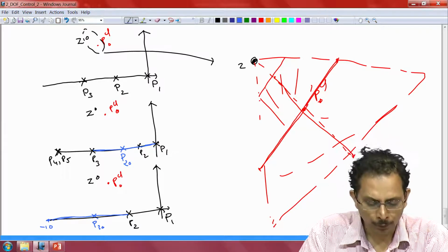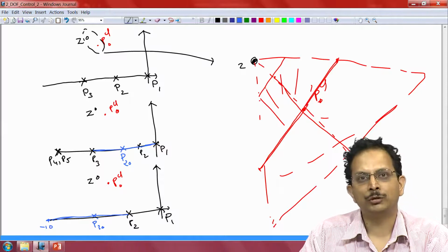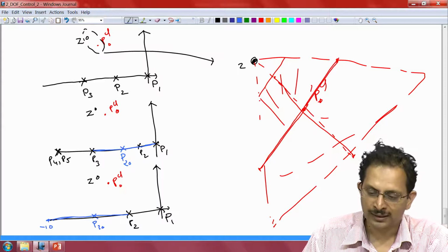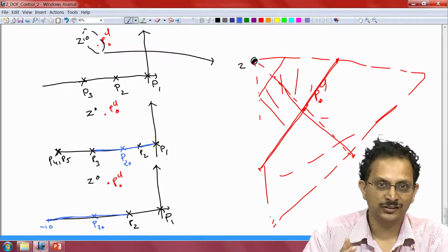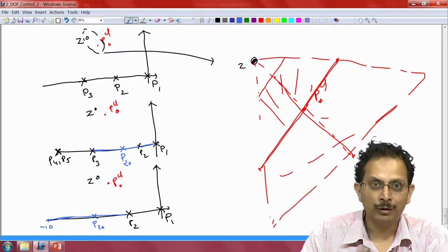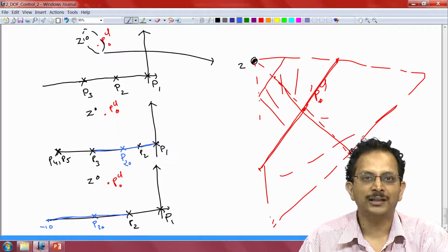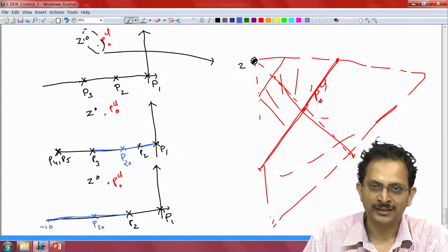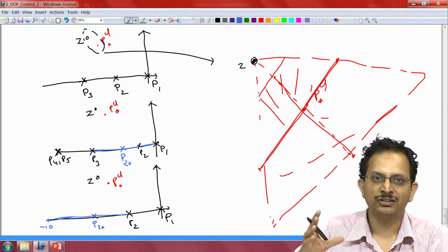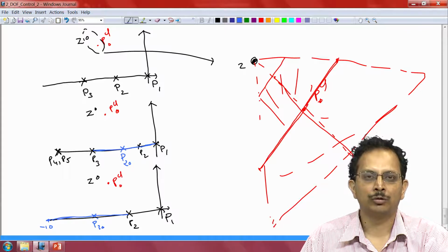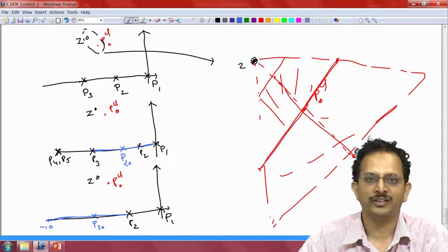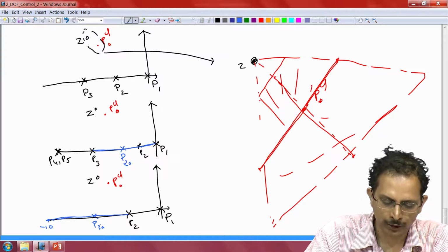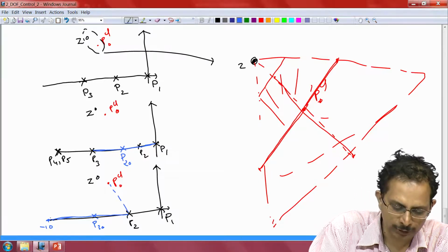If the third pole were to wander about, were to change its position with respect to its nominal value, which is P3 naught, then we know from the analysis that we have performed that when one of the poles of the plant were to change, then the closed loop pole varies in such a manner that the triangle described by the extremities of the closed loop pole positions with respect to the point Z is similar to the triangle described by the extremities of the point P3 naught with respect to the point PCL naught.